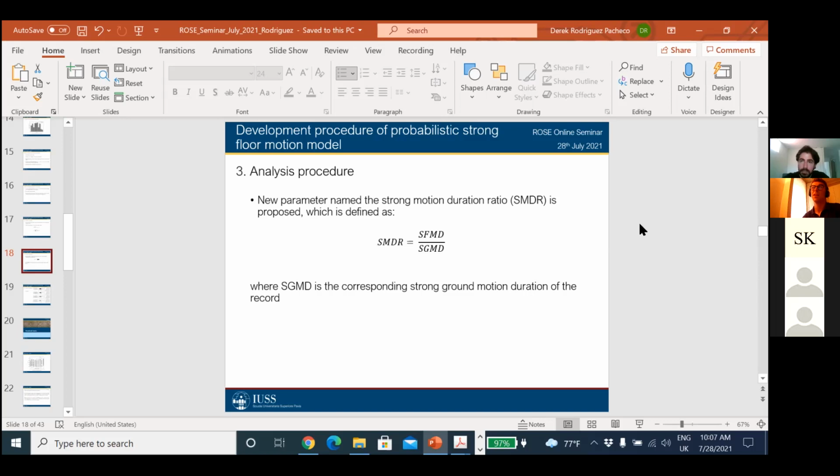But given that some non-structural elements may have vibration periods which are not very rigid, they could be very flexible, do you think this could be extended to, let's say, spectral acceleration, so the response at higher periods, not floor acceleration, but the response at 1 second, for example? Would you see some value in that, and do you think it would make a difference? It's a very big question, I know, but it's a curiosity.